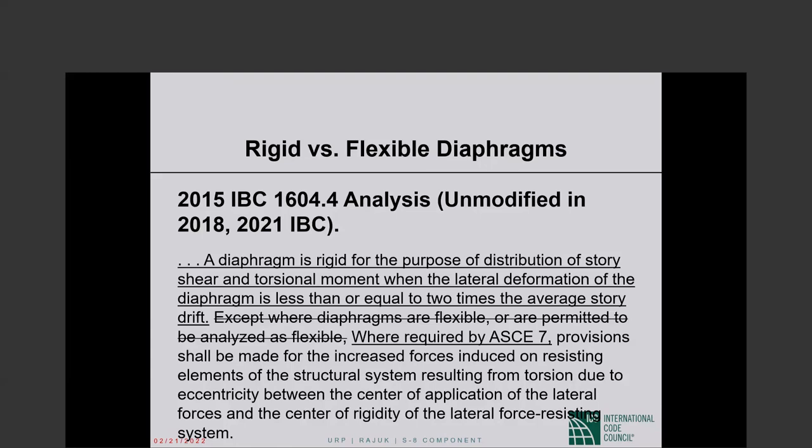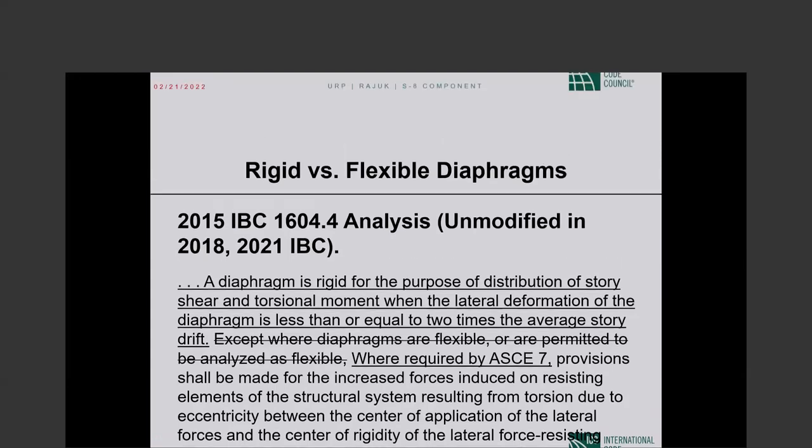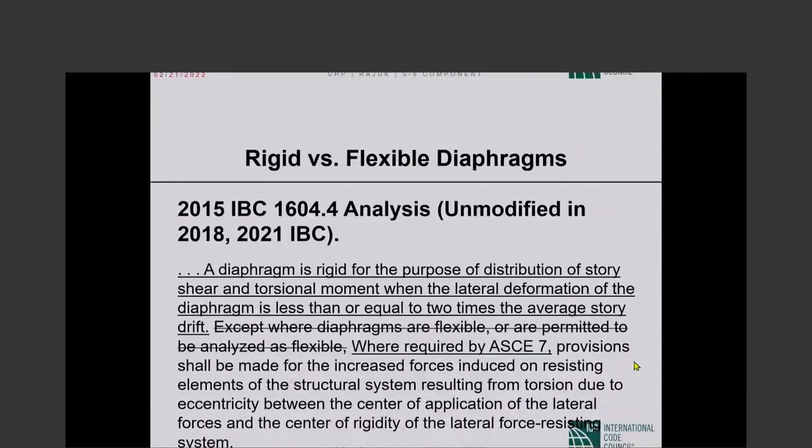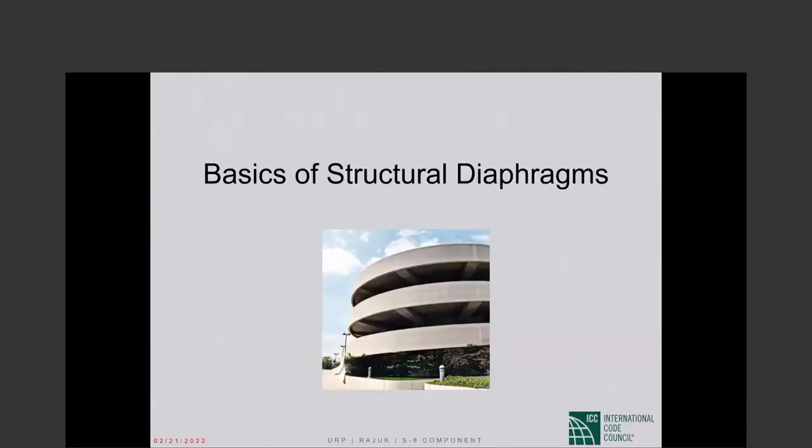And I mentioned previously that the code controls over the standard. So you can legitimately say that since this provision is in the IBC, we do not have to go by this AC 710 requirement of semi-rigid diaphragm modeling.